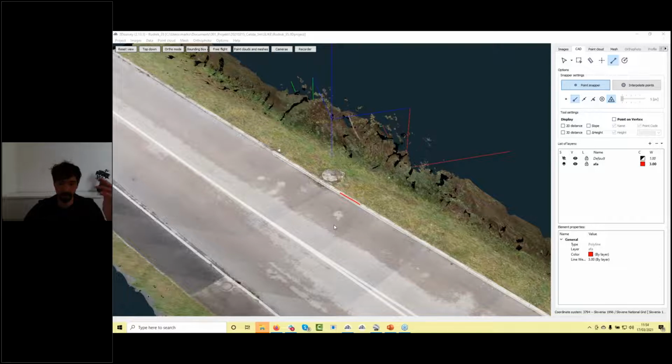But nevertheless, Phantom 3 Pro also works. If you take a bit more time, place more ground control points, fly maybe a bit lower, because I think it has a 12 megapixel camera. I would go at 60 meters or 50 meters, something like that. You can also go with this one, definitely. Okay.